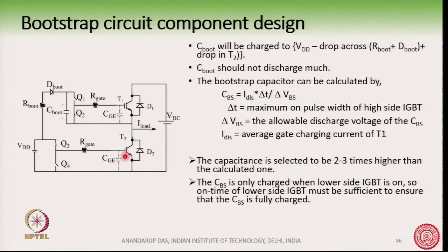You should also note that the lower side IGBT should be turned on for a sufficient amount of time, so that this capacitor will be fully charged up.